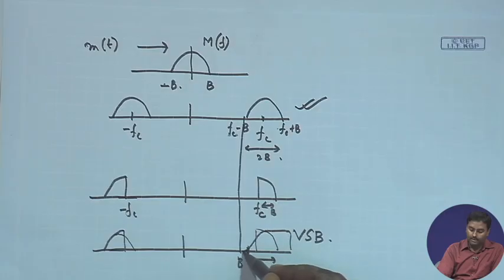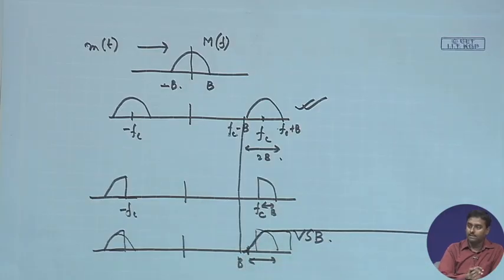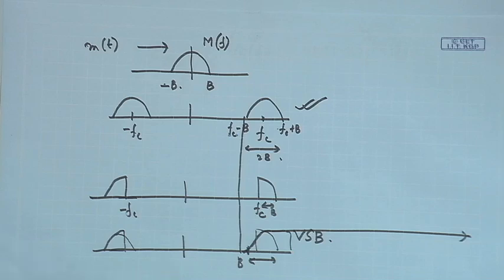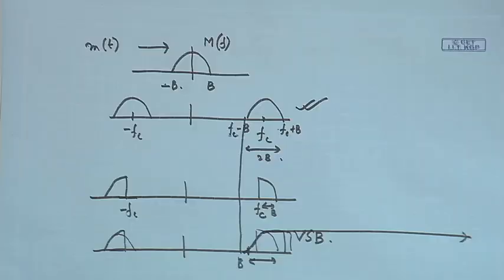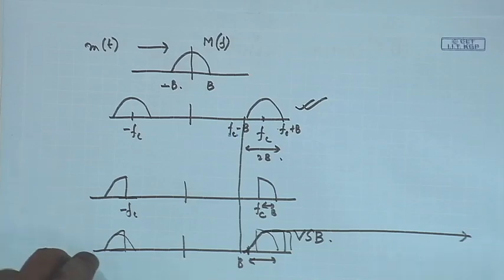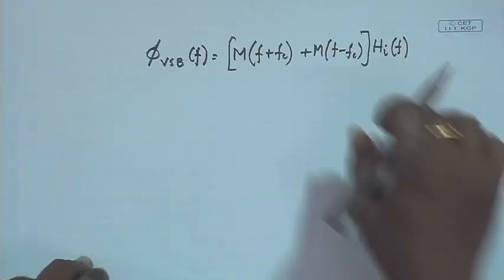It might be high pass, starting from here and running over the entire band, but later we will understand that is not really required. We do not have to include that entire band, so we can end it somewhere. We put a band pass filter with typical characteristics, which we define as HIF. So to generate my VSB signal, I modulate it, followed by a band pass filter.